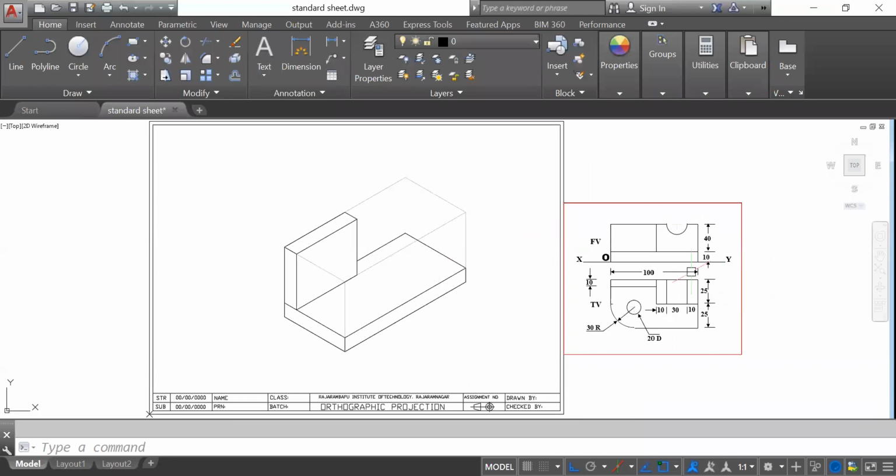You can see this one. This part you have to draw. So how it is required to draw: this side it is 25 and it is throughout, right? So I will just connect this to this and this side 25 mm. Control E button, which should be in the top view mode. Okay. So it is 25 mm. I'll just prepare a block first. This side it is 50 mm. Then connect up to here. Okay. That's it. So here it is required to take blocks again.